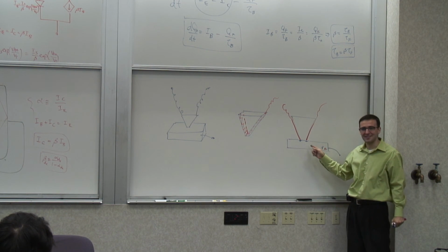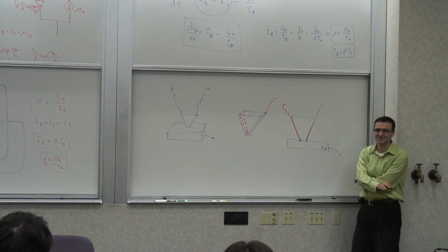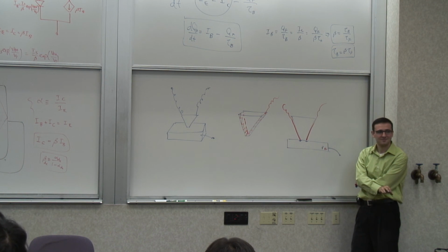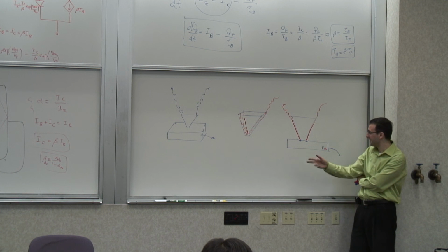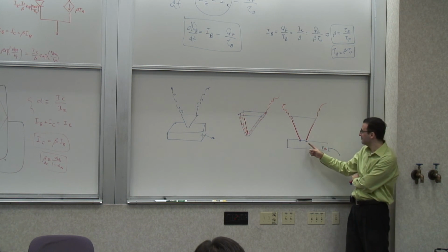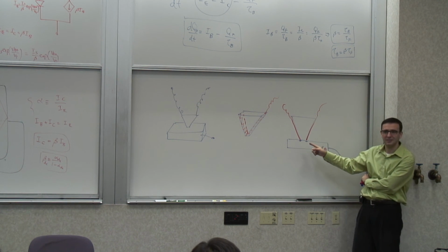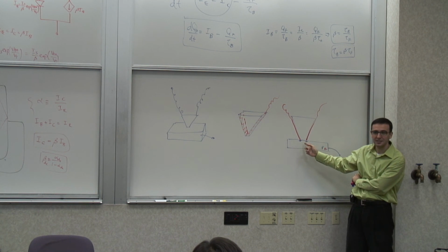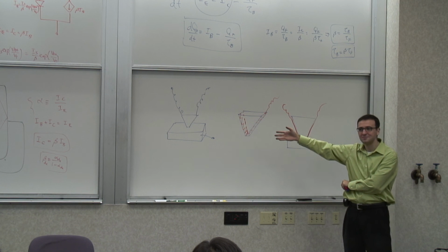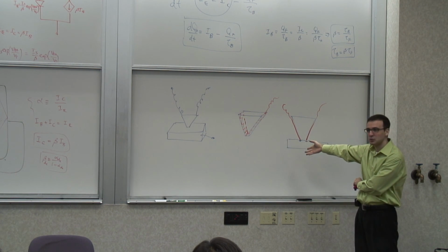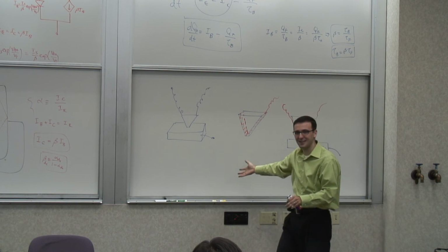So what's bad about this? Let's talk about that. What are the bad things about this transistor, compared to what we made before? Well, the base is huge, the size. And the emitter injection efficiency can be lousy, and your Early effect is going to be huge. Doesn't matter. You make something that affects everything else that follows.